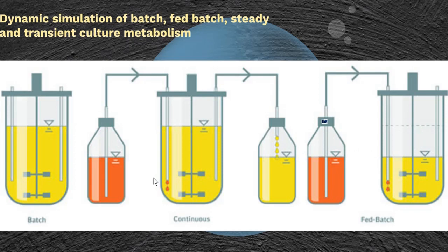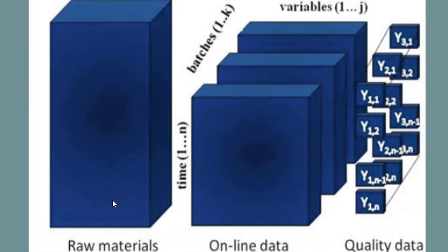The key important parameter to be considered in continuous and fed-batch systems is the dilution rate. As the medium is fed into the reactor, the reactor gets diluted and in turn affects the yield of the process. In the simulation studies, the substrate being used for a given bioprocess, the variable parameters and the quality of output can be simulated in such a way that we can predict the yield of a given process, including the process economics and the efficiency, without using more chemicals and manpower.